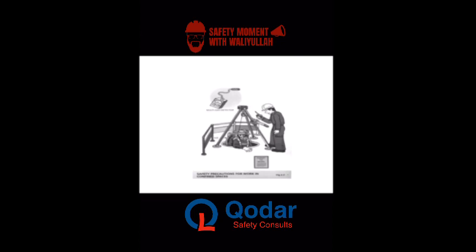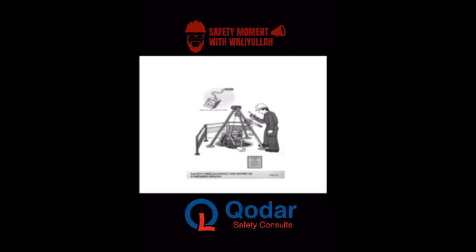This is a pictorial illustration of someone who wants to enter into a confined space. You see a watchman who is there. We also see a multi-gas detector. We need to see how well the personnel is kitted. We also saw a permit to work system there on that page. This shows that it is very, very vital for all these things to be in place.